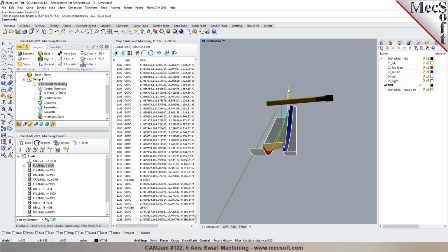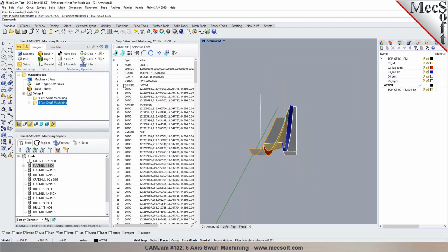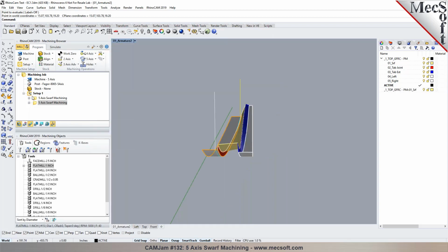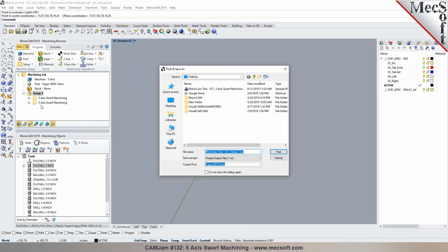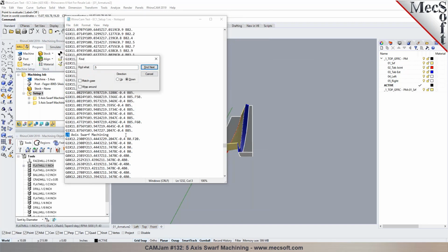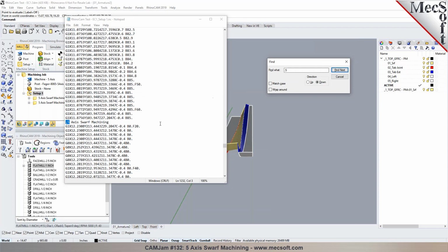And then from there, it transitions over to the next starting location, which should be over here. And you can actually see all of these coordinate values right in here, even before you post-process the code. Yeah, that's lovely. And I can post both the operations into one output file. So when you're programming, it could be two operations. But when you post it out, you see the first operation in here. So the next operation, you can see it goes from right here into the next starting location.